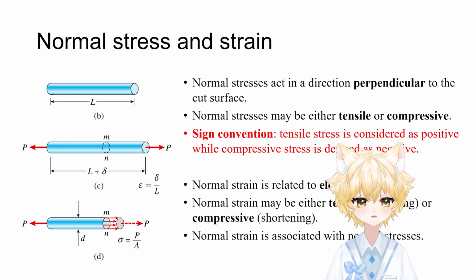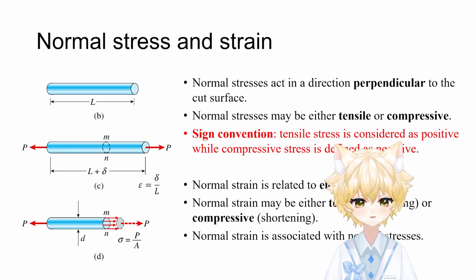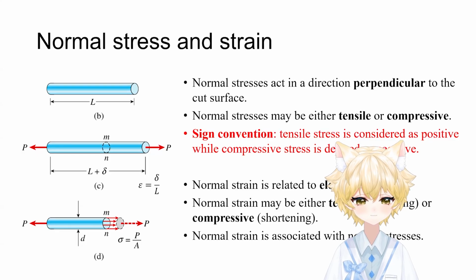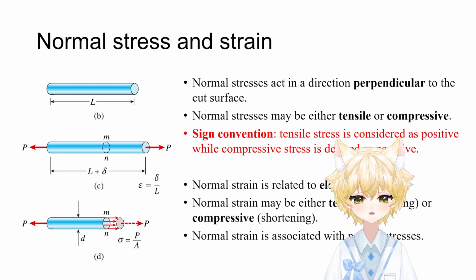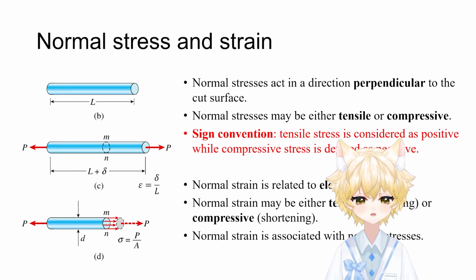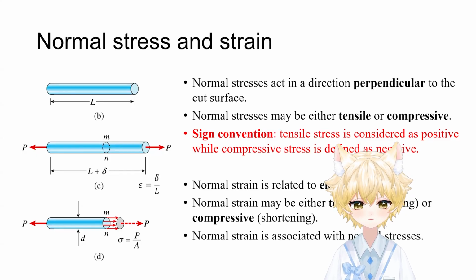Now, look at the text in red on the slide. This is the sign convention. We define tensile stress, namely pulling, as positive, and compressive stress, namely pushing, as negative. I want to emphasize this is not a law of physics. Nature doesn't care about plus or minus signs. It only cares about forces.